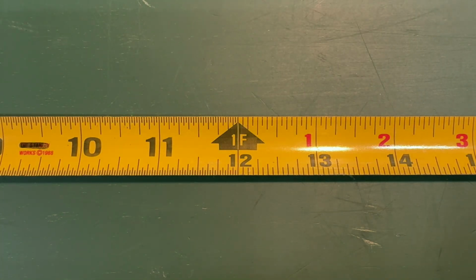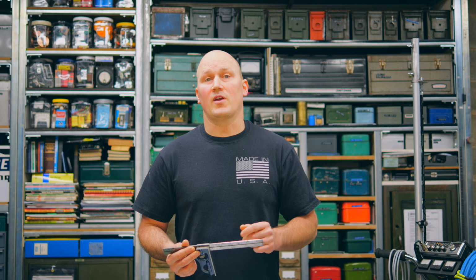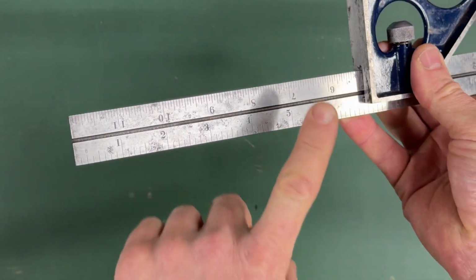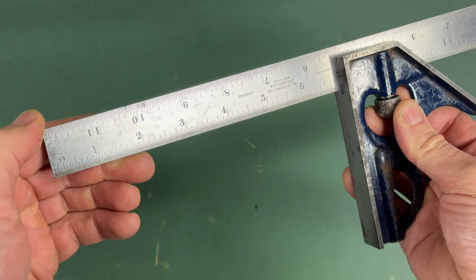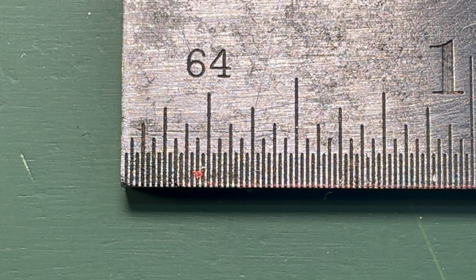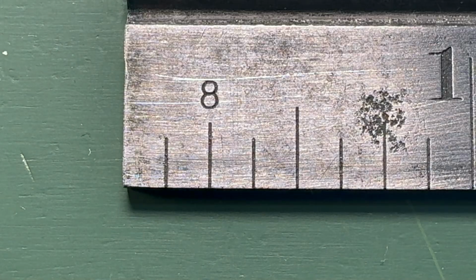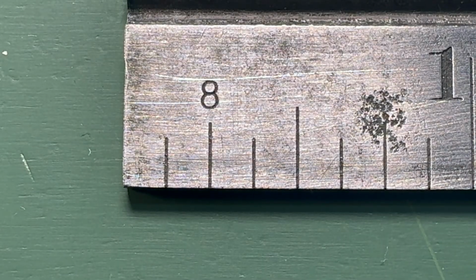This machinist square has a ruler with the 4 commonly used fractional graduations, one on each edge. We can measure to 8ths, 16ths, 32nds, or 64ths depending on how precise we need to go. And yes, we could use the 64th scale for all measurements, but if we only need to measure or mark to the 1/8 or the 1/4, it's easier to use the less cluttered scale.